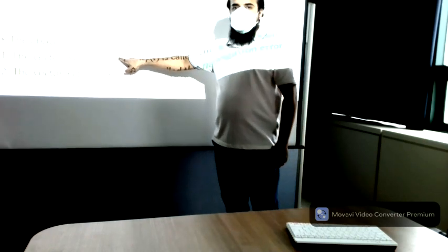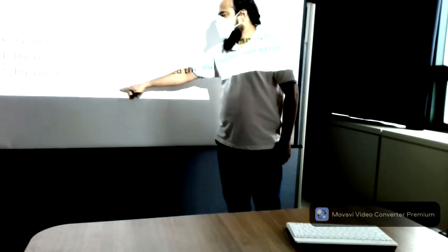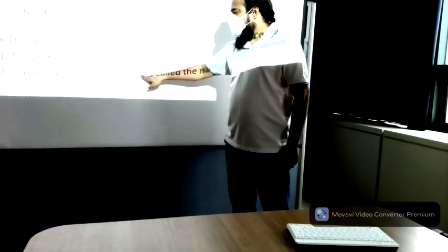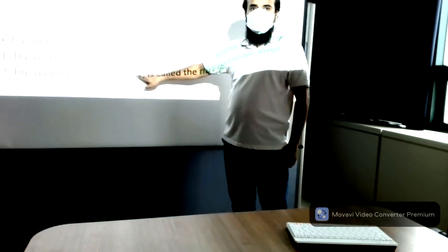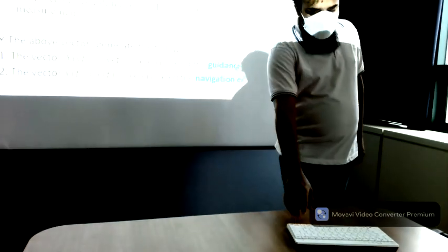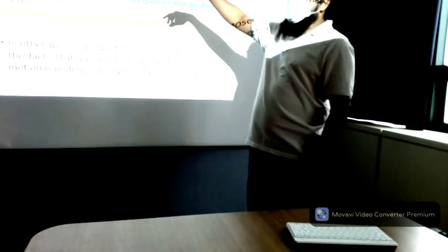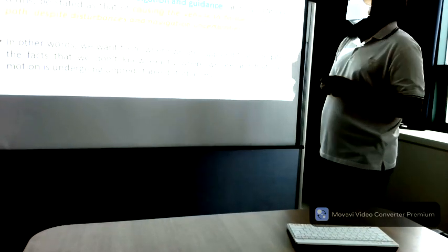This is the actual vehicle state vector and the reference state vector, and this is the vehicle state vector and the estimated state vector. So why do these errors come? The guidance error is the difference between where the vehicle is located and where it is supposed to be. It is generally caused by disturbances acting on the vehicle, such as wind, gusts, currents and thrust misalignment.